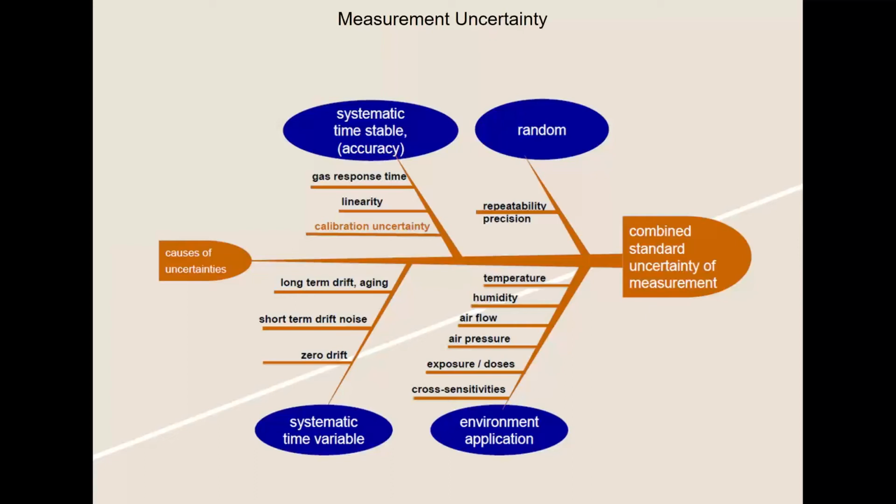What is the temperature range that the sensor might be sitting in? Is the sensor going to be sitting in an area where the humidity is over 95% relative humidity? And if so, what do we do then? So all those things need to go in to not only selecting the proper sensor, but also knowing what might cause an alarm and what things to look for if an alarm does occur.